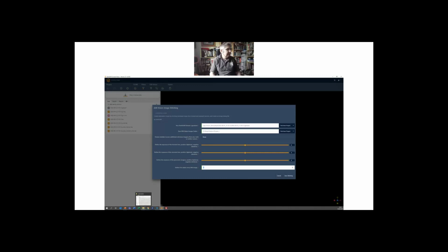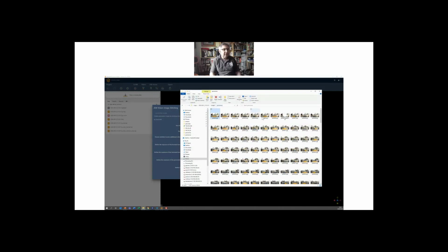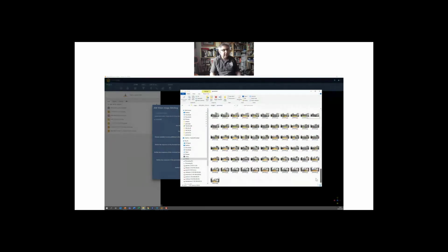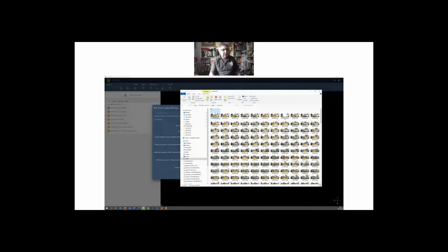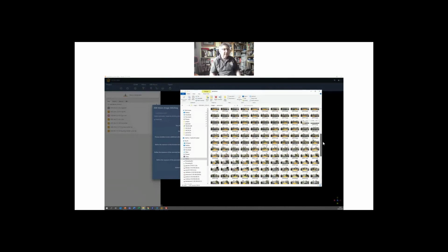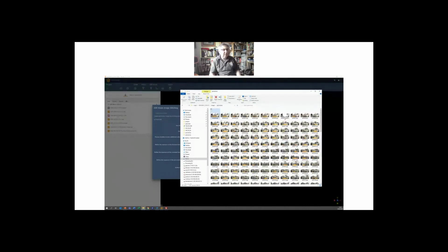So what you should see when it is running, you can check in your panoramas folder. You'll see a group of 5 or 10 images. The unrectified versions are brought into this folder. Then you can see them being rectified and joined and then deleted. And that's another good way you can check that the stitch is progressing. Just look in your panoramas folder. Panoramas should be being created.